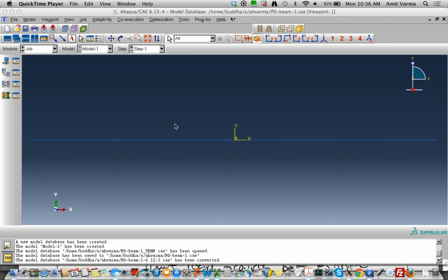And we were able to draw out the total load displacement curve. That's the P versus V curve. And we just summarized some bullets. We said that all we did ever was elastic analysis. We didn't really do any inelastic analysis. We just did elastic analysis, introduced a plastic hinge, continued with an incremental. Since we know how to do elastic analysis, that's really, really doable. That's something that we can do.